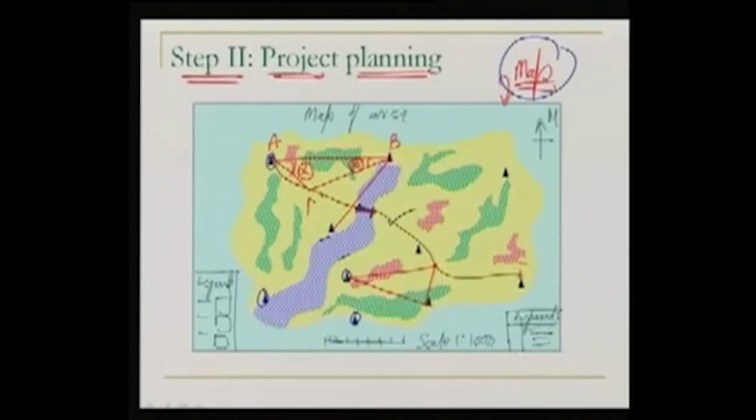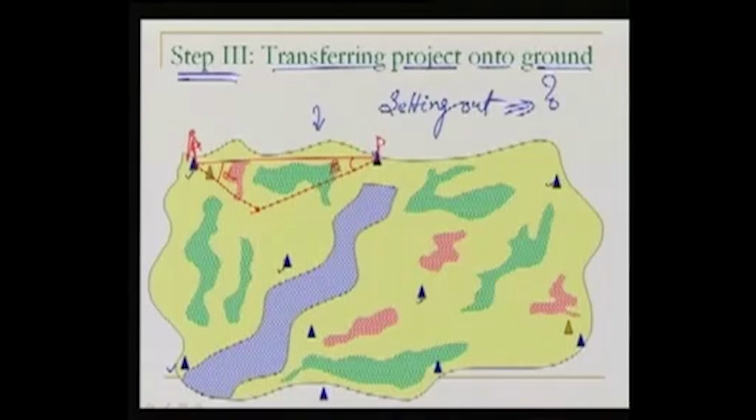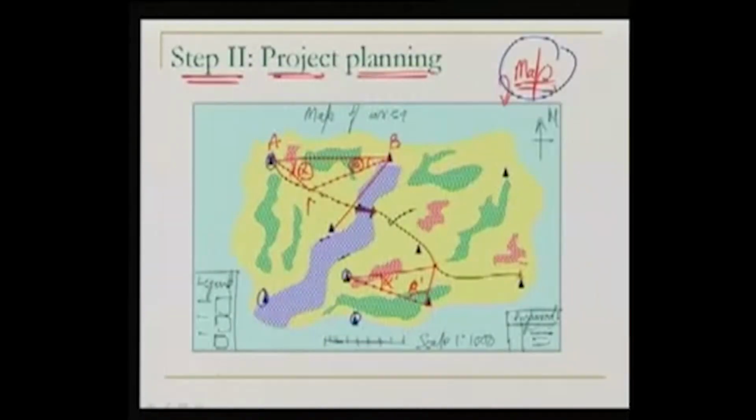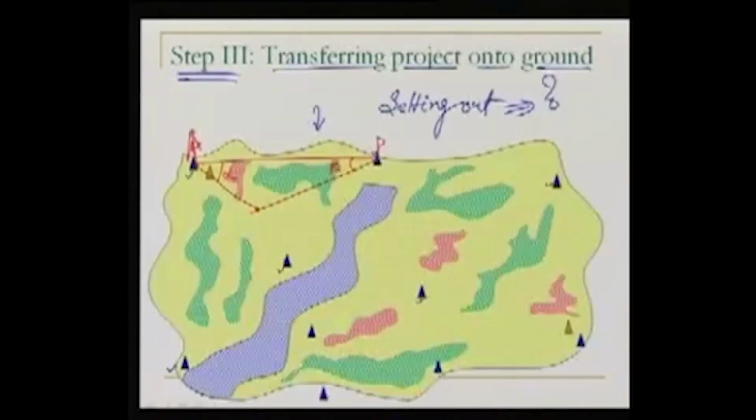control points. I'm just making use of two angles, alpha dash and beta dash. So a point here can be located if you go to the same set of stations, from these two, alpha dash and beta dash. So this point is also located. Similarly, we can locate various points of a project along with the bridge, and the entire project will be located there on the ground.